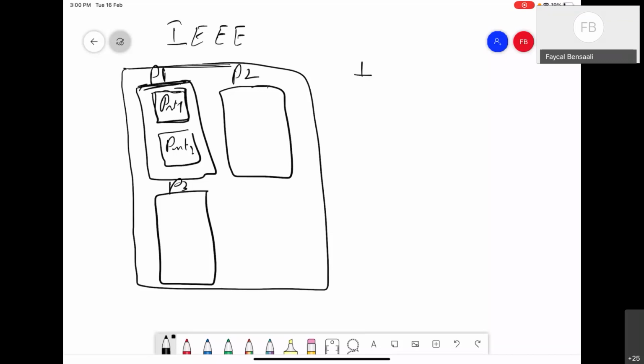And how do you do this? By using the keyword use and then IEEE and then dot, for example, package 1. Of course, there are names for each package, and all the packages and what you have inside each package is available online. And then you specify which part. Or if you want to have access to the full package, you can just put all here. This means I want to have access to all parts of package 1. And that's it. By doing this, you will have access to the package.